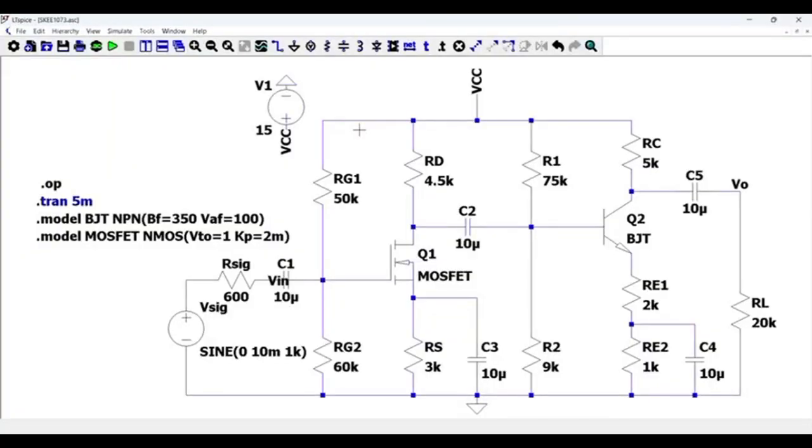Now, let's move to the DC operating point analysis of our multistage amplifier. In DC analysis, the fundamental rule of capacitors is that they act as perfect open circuits. This is because at DC the signal frequency is 0 Hz. A frequency of 0 yields an infinite AC resistance. It will completely block any DC current from passing through.